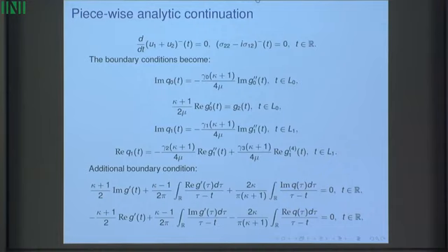Again, if it's piecewise analytic continuation and there is no real material in the lower half plane, then how do we continue them analytically? It depends on us, actually, to some degree. It's our choice, and there are several standard choices to do it. Typically, if you have stresses given on the boundary, you would continue stresses through the contour and let the derivatives jump. If you have derivatives given, then you do it the other way around.